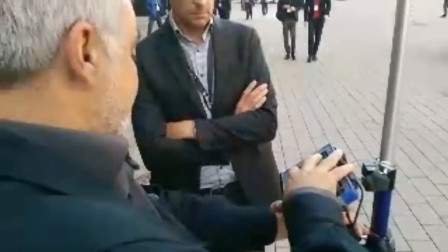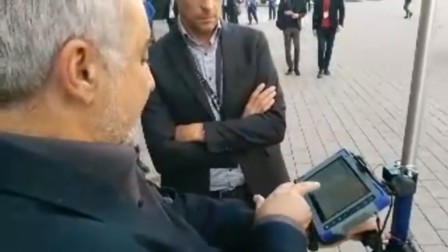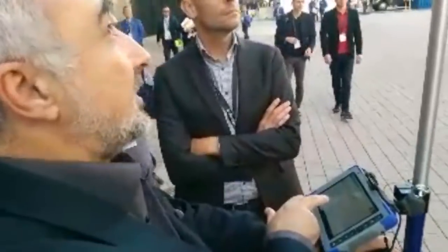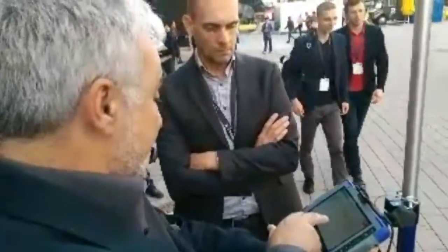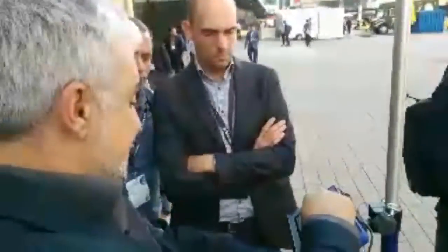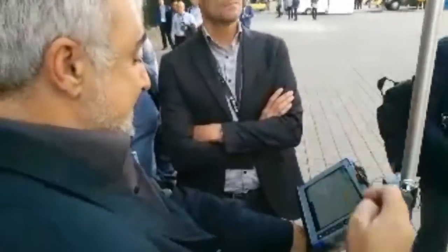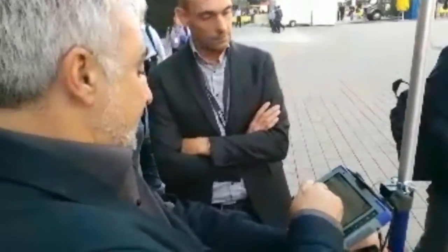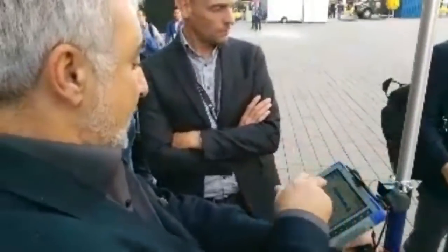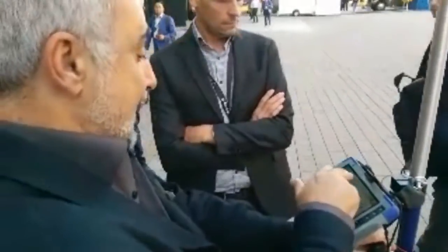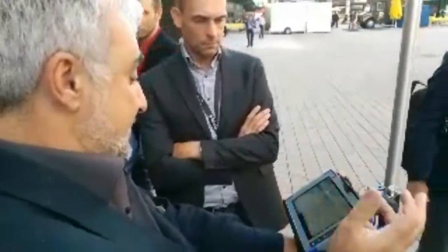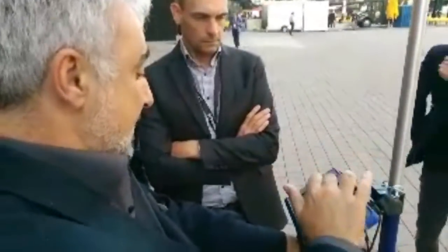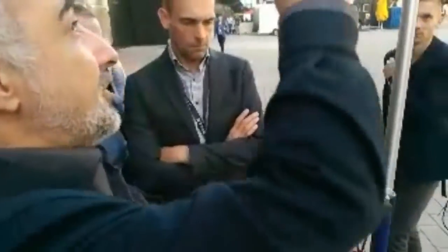So first, we are configured to the total station, we are connected, we have the green check to say I'm good, and I'm connected to CR+. But I'm not connected to GPS. You see, BRX6 is my last receiver. So I say, well, I'm going to configure that. It is by default going to BRX6. If no changes, I will just reconnect and green check to apply settings to the receiver.